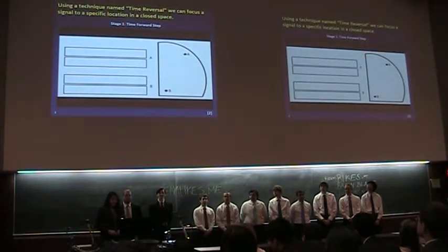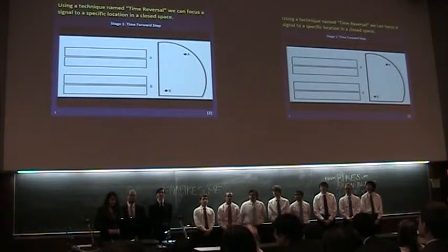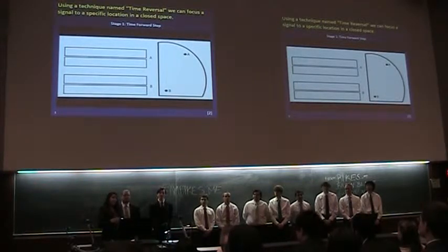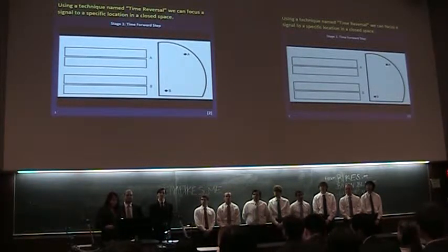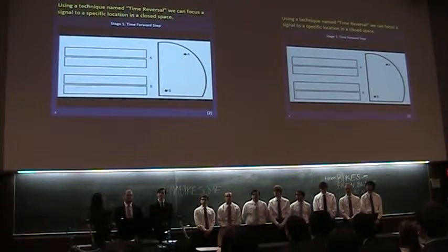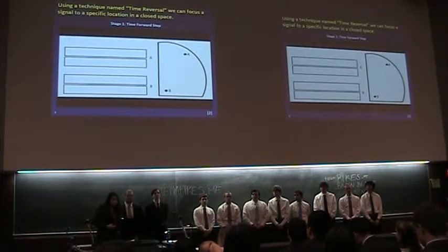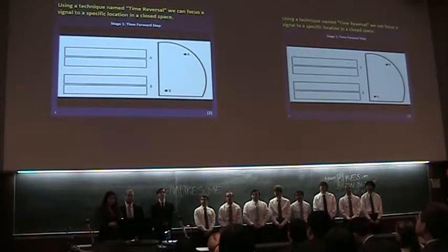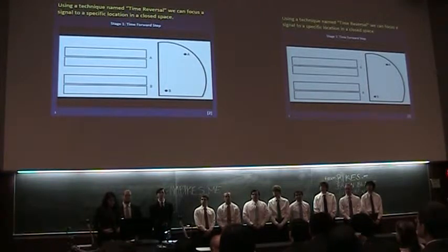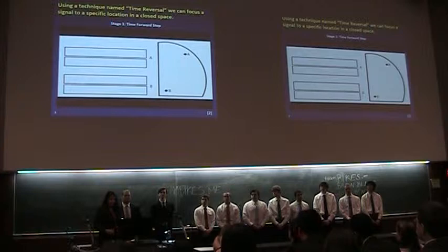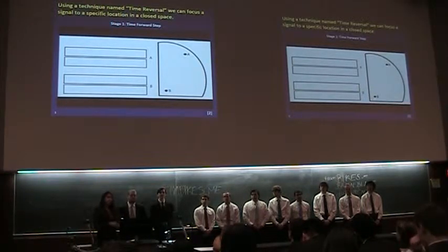So, time reversal is a signal focusing technique. You can think of its purpose as responding to a received signal and communicating with the sender, and only the sender. So for example, here we have 2 points, A and B. You can think of these as a model for an antenna. And these antennae would send and receive signals. So if A sends out a signal and B listens to it, B can then respond to A and only A, since the signal converges at that point alone.